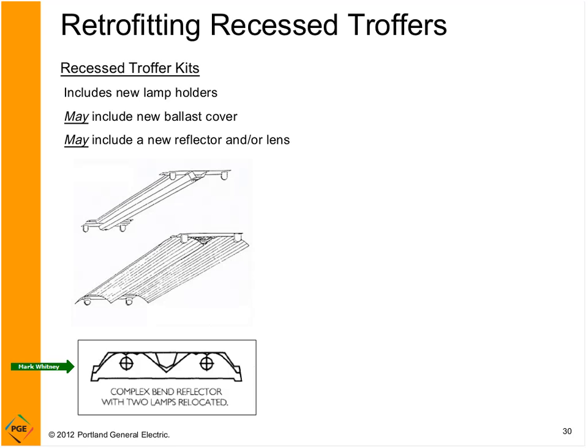With a reflector kit, you're going to have them repositioned more where they should be for a 2-lamp fixture. And if you have a kit that has a reflector, like this illustration, you're going to make that fixture more efficient. More light is going to get out of that fixture.